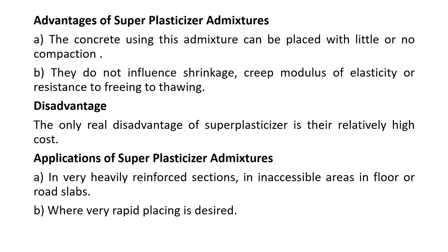Advantages of superplasticizer admixtures. The concrete using these admixtures can be placed with little or no compaction. They do not influence shrinkage, creep, modulus of elasticity, or resistance to freezing and thawing.